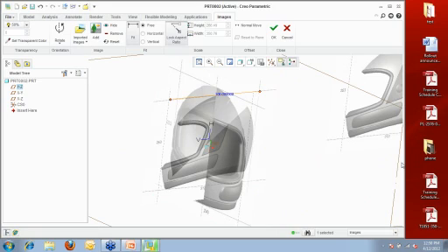No. If another user does not have ISDX, Mike, no, they cannot edit. Now, when you say file, obviously it's just a Pro E file, so they can make all the parametric changes they want. But they'll see the style feature, but they cannot change that style feature in any form. So yes, they can open up the Pro E file and do anything parametrically to it after the fact. Let's say you're just the ISDX surfacing guy and everybody else made solids. You could make the ISDX features, but they could just add the parametric features like a thicken or a shell or a solidify based off of it. So yes, they can edit the file itself, but not the ISDX tool.